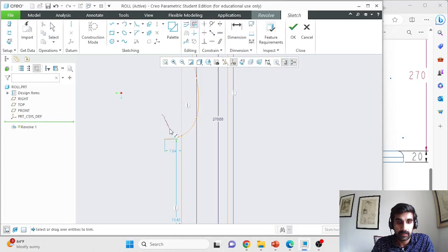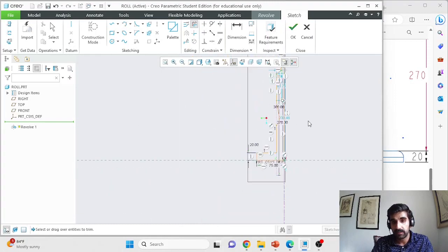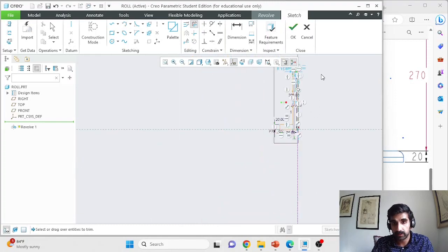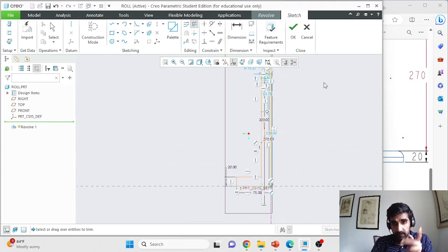Delete segment, and then just run it through the segment that you want deleted, which gets highlighted. I wanted this additional segment to be deleted, and by pressing the left mouse button and dragging it through the feature, that feature has been deleted. And hopefully now when I press the center mouse button, this will be highlighted, which it is.